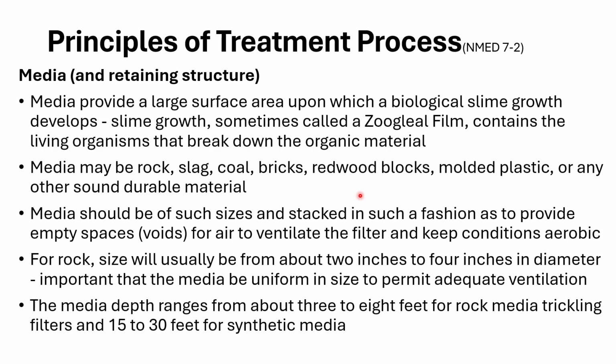Okay. So the media, the first of the basic components of the trickling filter system. Again, the media serves to provide a large surface area so that biological slime is going to grow and develop. Again, I have a problem pronouncing it, the zoogloeal film.